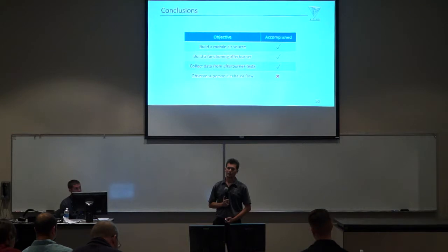The only objective that we did not meet during this project was to observe supersonic exhaust flow and to measure it due to our pressure rise. We came in shy of our pressure rise, and therefore we were below choke flow at the nozzle throat.